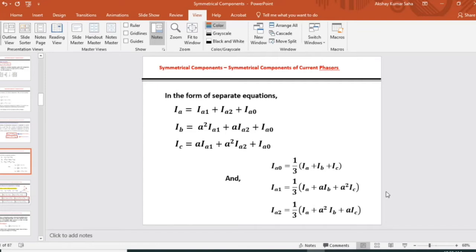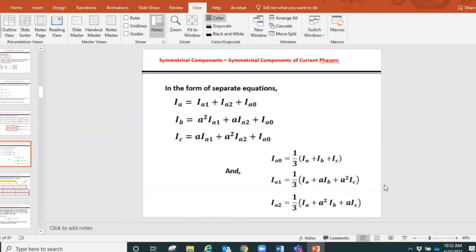But for the impedance, it's a bit complicated because impedance will come from the actual device or equipment that we connect to our system. It can be a transmission line, a series impedance, a motor, or a transformer. And with transformers, there are different conditions that come with the connection. For example, with a three-phase transformer, we connect them in star, we connect them in delta.